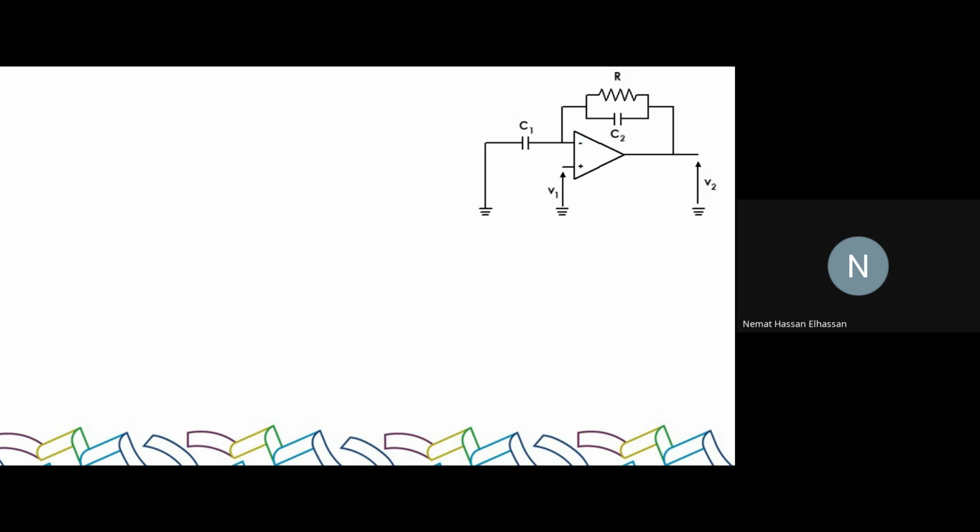Here we have an example of that. Do you notice the difference between this one and this high pass filter? The only difference is that the component here is a capacitor instead of a resistor, right? And this simple change will change the filter from low pass to high pass active filter. So let's calculate: the output is V2, the input is V1. Now let me ask you the exact same exam question. What type of filter does this circuit implement, and justify your answer?